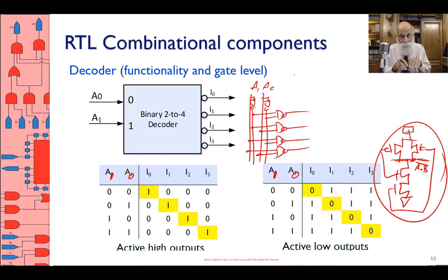Active high outputs. I'm not going to put an inverter. Once again, because putting an inverter on this output means that I have to have these two transistors also added to each of these outputs. I don't want to do that. Why waste two transistors? Not only that, why waste a delay from NAND to transistor? So my circuit not only has two more transistors, but it also has longer delay.